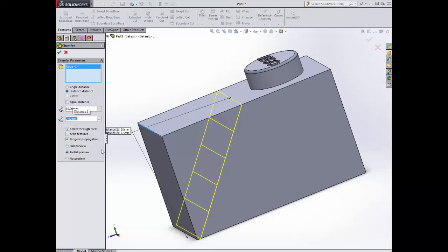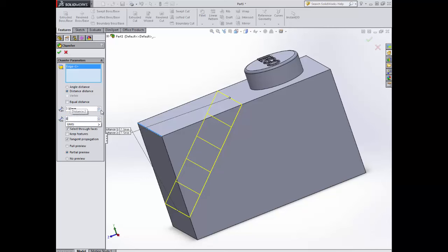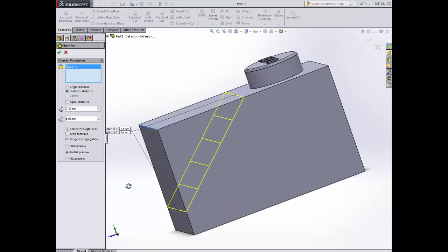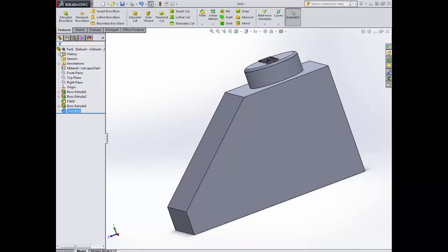and then in the top. Now you'll notice on the drawing that one of them is not 7.5 and it's this one, so I'm going to change that. As you can see, you can adapt and amend and change the things in these particular parts of the file with your chamfer tool. Check it's right with the preview and then green tick it. That gives us our overall shape, so now we need to consider what's happening on the inside and the bottom.